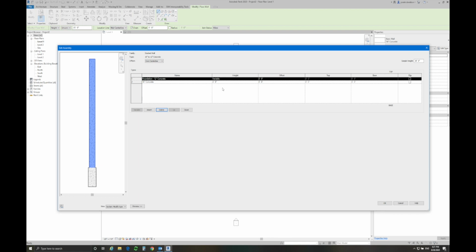This option didn't exist when we were creating our basic walls, and there's a good reason for that. When you're creating a basic wall, when you insert it into Revit, you know that's where you define the height. You can either set an unconnected height or connect it to one of your levels. However, with a stacked wall, an element has to have a predefined height, and then there needs to be another component that's adjustable, just like a basic wall, or variable.